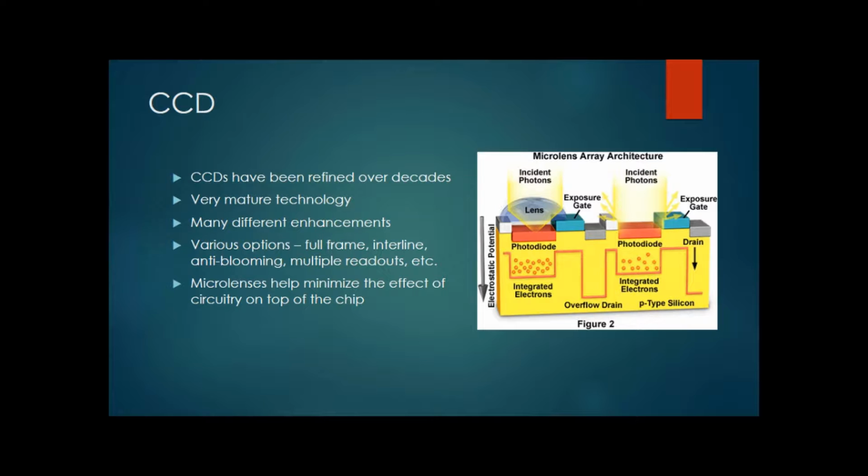The disadvantage is now half the chip is taken up with these readout columns, which means that there's less room for electrons, and there's less fill factor, which again is what the micro lenses help with. So the reason for using interline sensors is they eliminate the shutter, and they're faster. So there are compromises in the designs of the sensors.